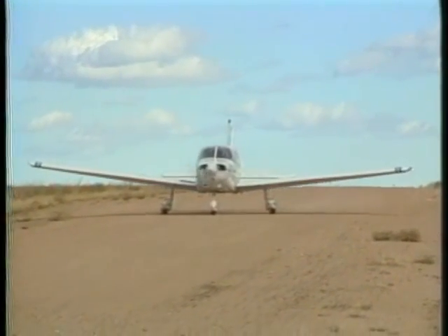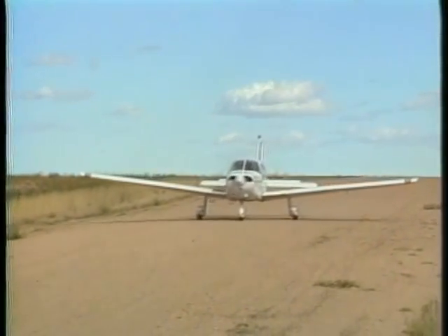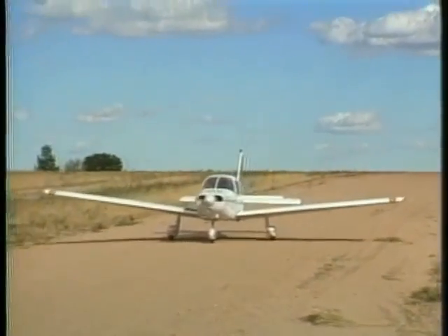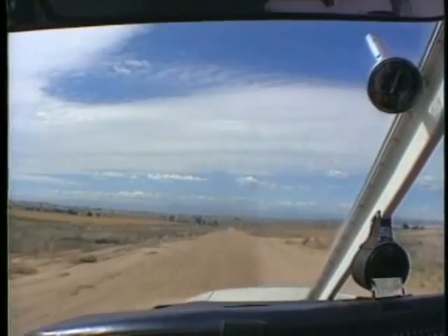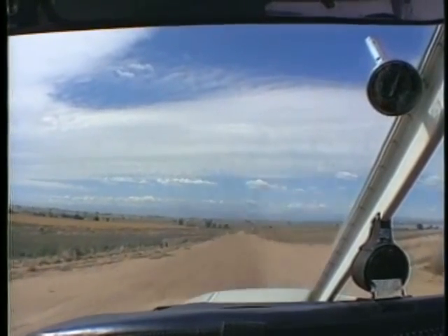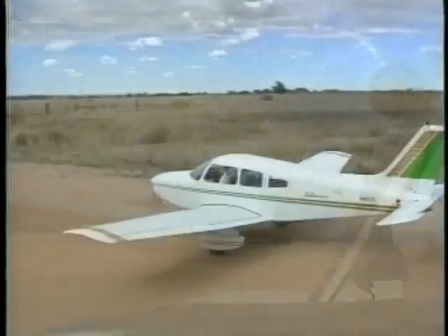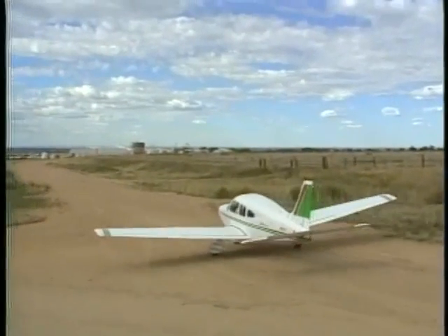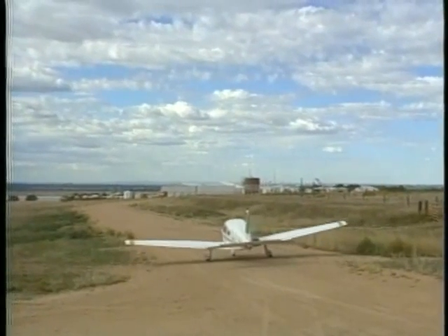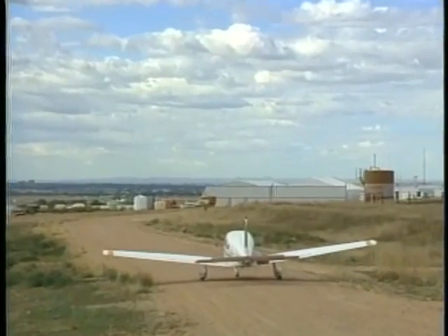Deceleration is usually rapid on a soft surface, so the use of brakes may not be needed. In fact, the use of brakes could cause the nose wheel to dig into the surface and the aircraft to nose over. Retract the flaps as recommended. It is usually preferable to leave the flaps down during the landing roll so your attention focuses on maintaining positive directional control. You will probably need to add more power than usual as you're taxiing to the parking area. You should also maintain back pressure on the control wheel. When clear of the runway, complete the after-landing checklist.